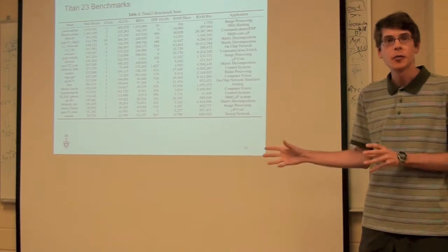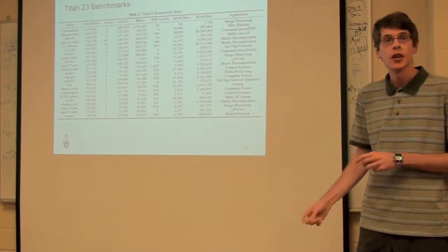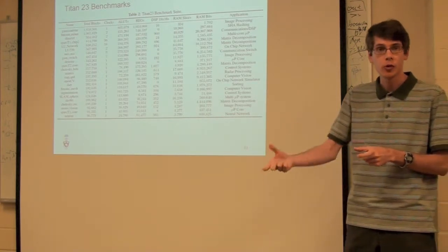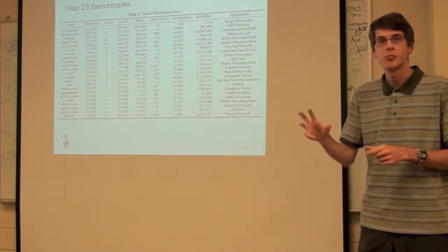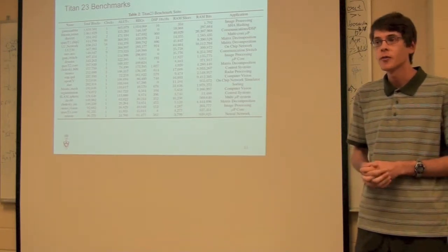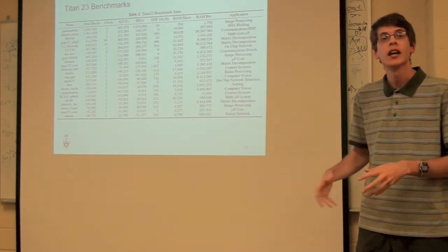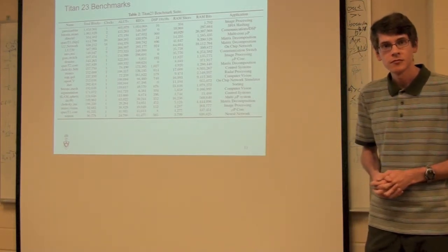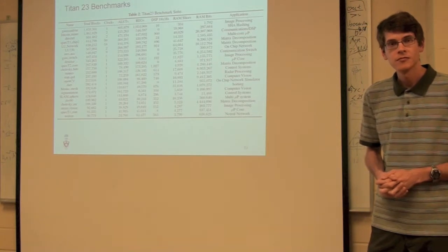One of the challenges is probably going to be multiple clocks, particularly since VPR really only allows you to have one clock per primitive. That can be somewhat limiting for things like RAMs that might have multiple clocks. So we're trying to figure out what the best way to go about doing that is. But let's keep away from the timing thing, which is a big nut to crack.